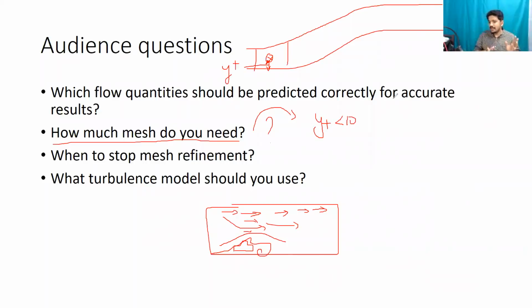So Jennifer, I hope this makes sense to you, right? When you're using the K epsilon model, it's a high Reynolds number model, so your y plus needs to be within a range of 30 and 100. And the reason why I commented that your simulations were wrong is because your y plus was 9,000, right? So if you have to get your y plus to 30 or 35, 60, say 90, say that your y plus should be 90.